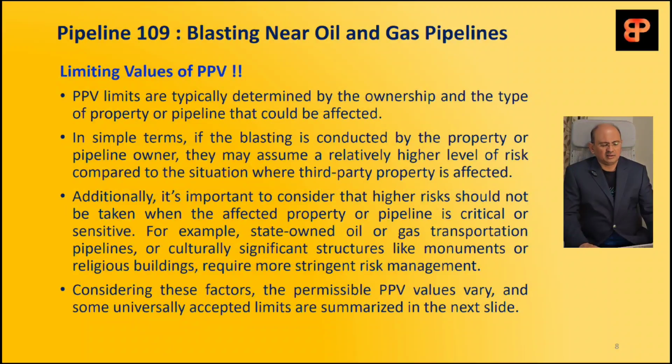So let us see. PPV limits are typically determined by the ownership and type of property or pipeline that could be getting affected. In simple terms, if the blasting is conducted by the property or pipeline owner himself, then he may assume a higher level of risk as compared to the situation where third party property is getting affected, which is obvious. Anybody will think about that logical aspect.